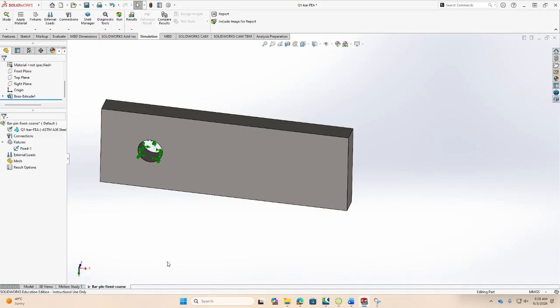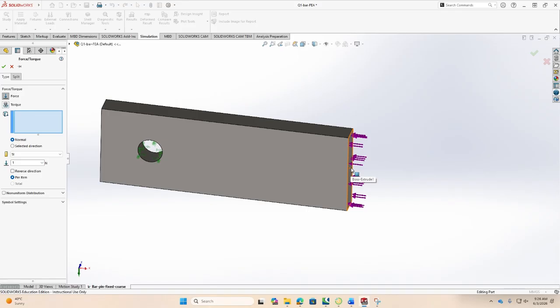Okay, guys. So now what's the next step? The next step is to apply the load. Let's now quickly apply the load, and the load application in this case is very simple. All the load is being applied directly on this edge because it's passing through this. We can have other methods of load application as well, but right now I want to keep things simple. I will just reverse the direction because it's not compression, it's tension. So this is the direction.